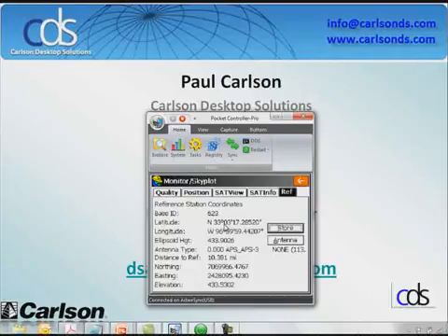Okay? If I'm on a network and I'm floating for 2 or 3 minutes and I don't fix, I want to come look at my distance to base, because maybe I'm 38 miles away from the base. Chances are I could sit there for a week and not get a fix at that distance. Okay, the baseline is just too long. So I want to come in here and I want to see that distance.